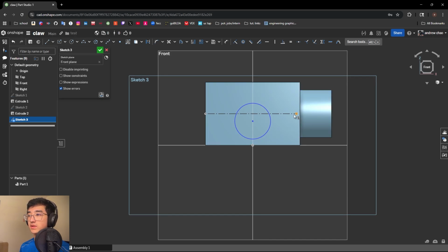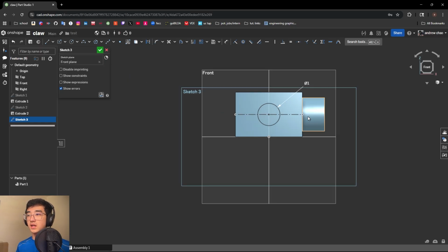We're going to do the same thing with this one. So coincident, point and point, and like that. So that now once we drag our circle, you'll see that it will want to snap into the midpoint of this construction line. So we're going to do that. Let's give our circle a dimension of 1 inch. And then we need to also define our axis, because we want to revolve it around some axis. We can't just revolve it around nothing.